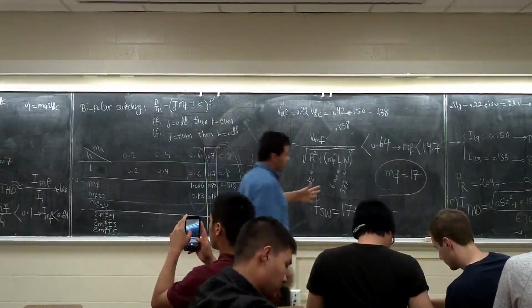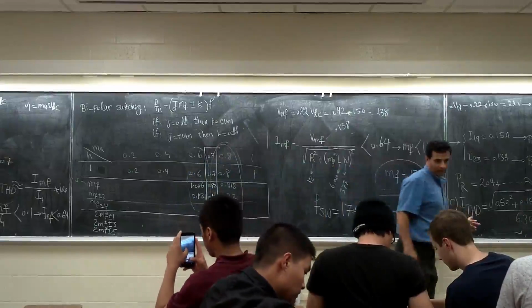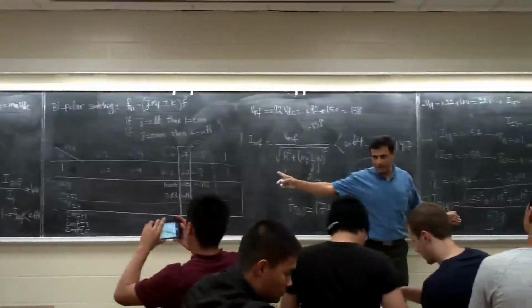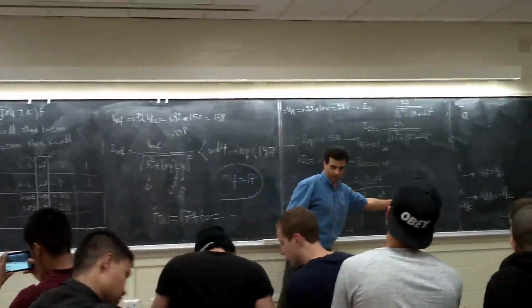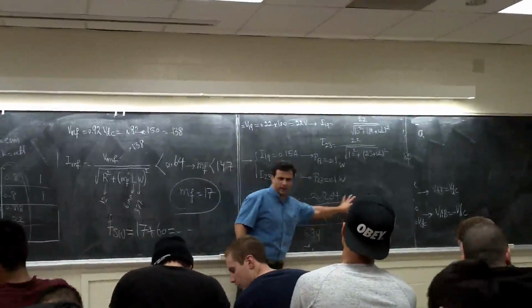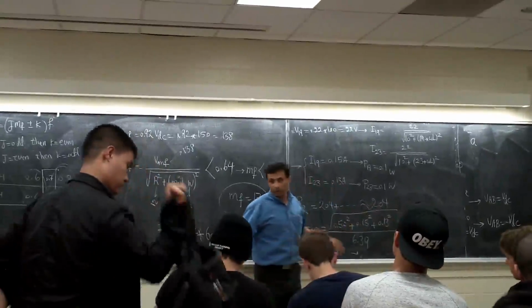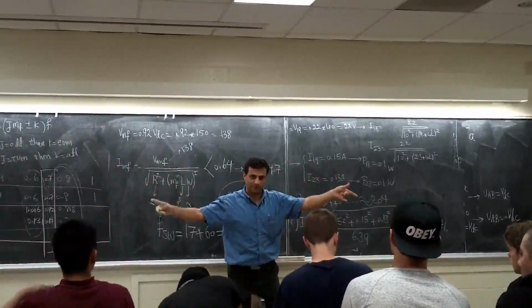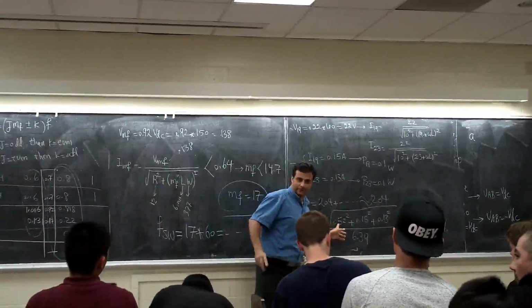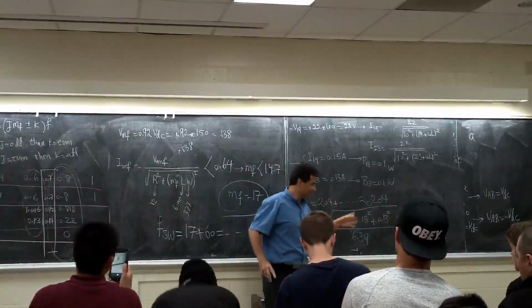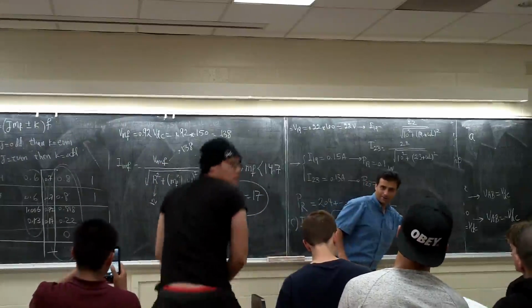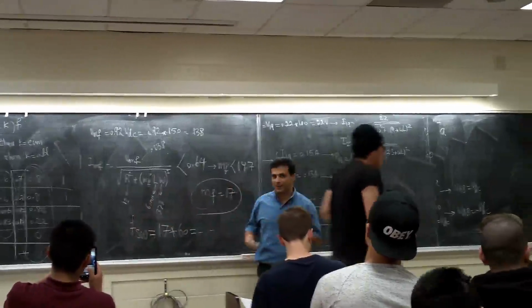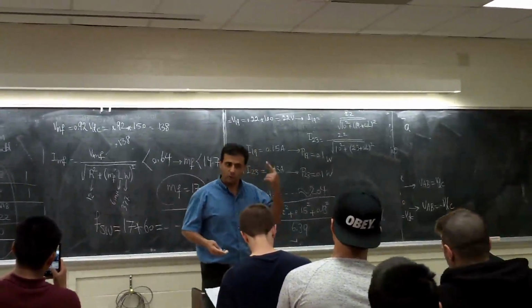Oh, here, do you remember what I said when I went through this one? For MF 21 divided by 8%, right? I explained this, and let's forget this one. Because if I would have gone with MF 42, two times, this one would be half, 0.26, and this THD would be smaller, right? So basically, if I want a better THD, I should go with a higher MF.